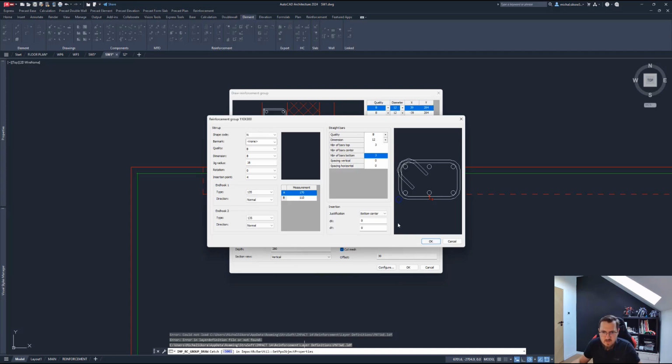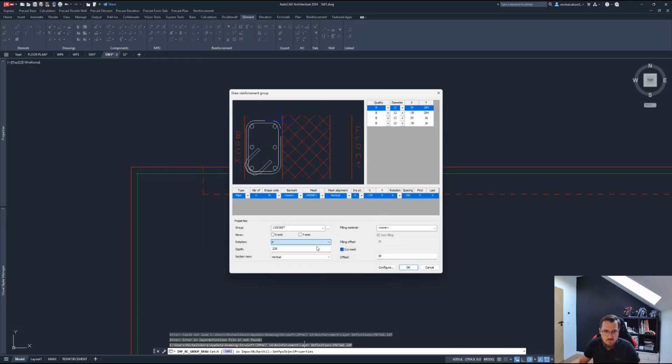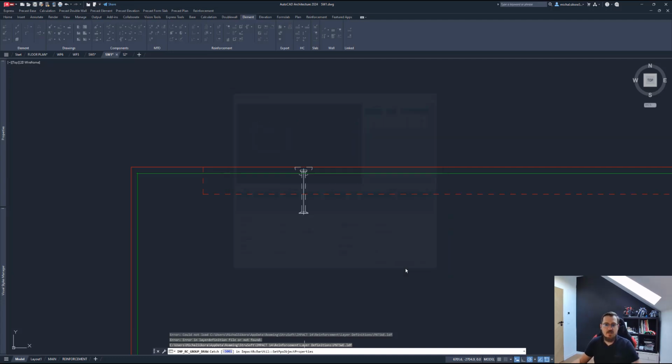And I'm going to then change the placement of that to say bottom right. Okay. And the rotation, I don't want any, like that. So you can see this is a preview. The preview, of course, does not include the panel thickening, so don't worry about that. That's because you can place it anywhere on the height of the wall, which will be then automatically reflected on the section, right? So let me do that. Let me now change that offset slightly, so maybe to 20. Yeah, that's too little of a difference. To 35. That was 225, so let's create more of a cover here. Let's go 250. That should be sufficient, and let's accept that.